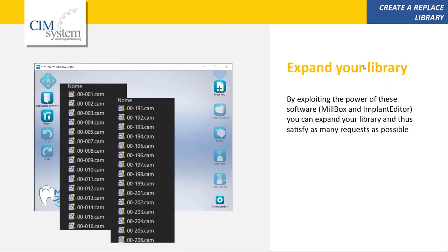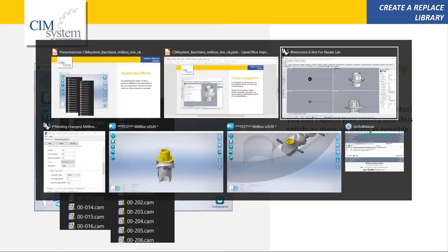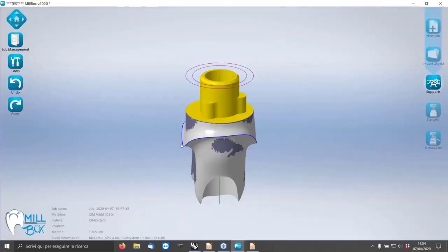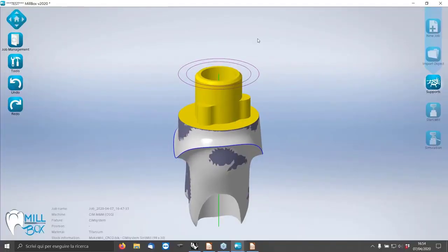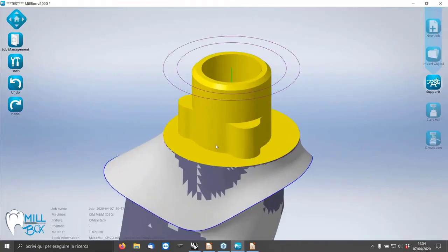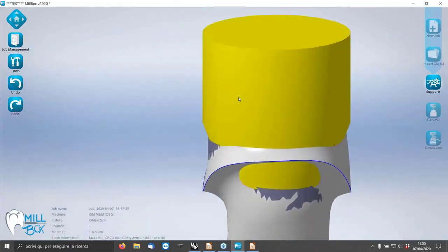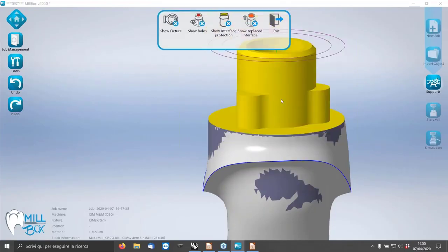Just one more question. I didn't understand the protection for sintering. Can you explain again, please? Okay, yeah, sure. When you go to laser melting, obviously it's not possible to mill and produce the connection part with accurate milling. So it's better to produce it with a cap, with this kind of cap, and after the laser sintering phase, go back on the machine and work by milling only the connection you have.